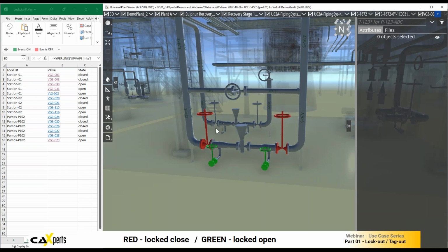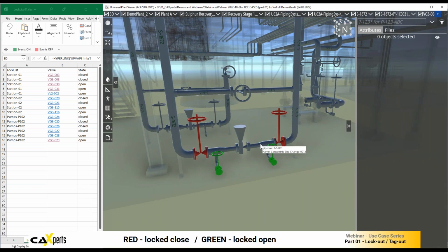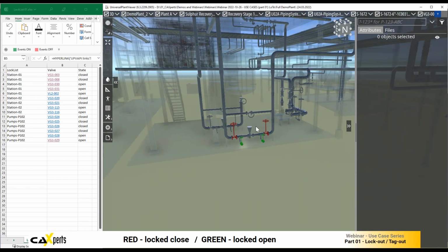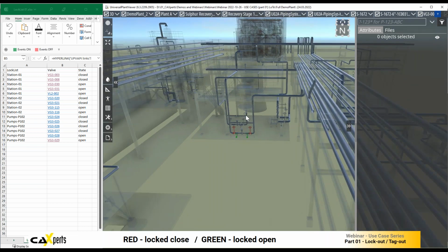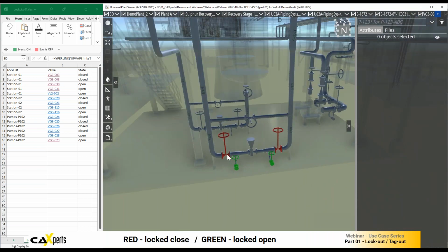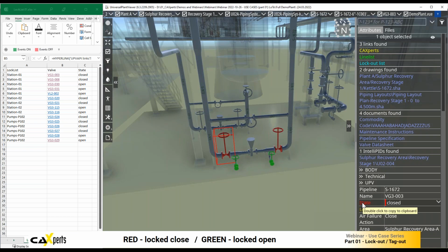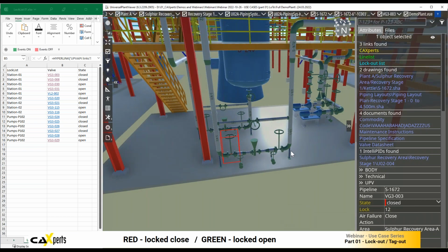So basically we could now exchange this control valve here in the middle. No matter where I am in the plant, I chose everything that's not regarding piping to be transparent and gray. Everything that's undefined is gray, and just our set states are colorized. If we want to revert this, all we have to do is double click on state, and we're back to the regular coloring.